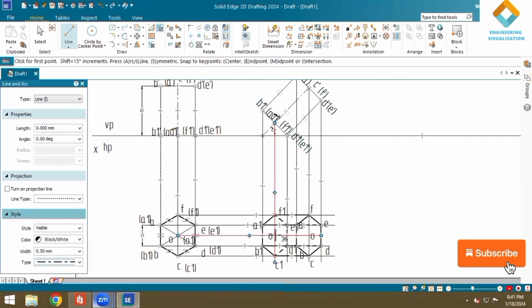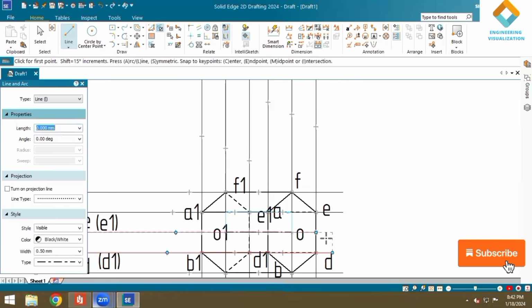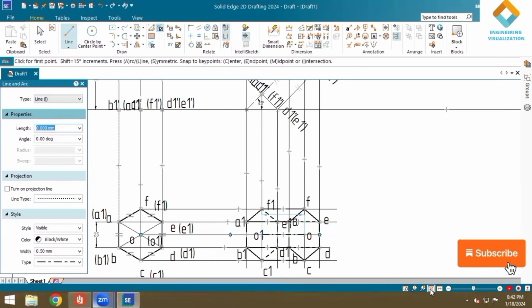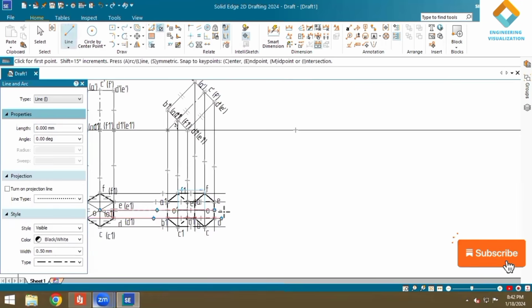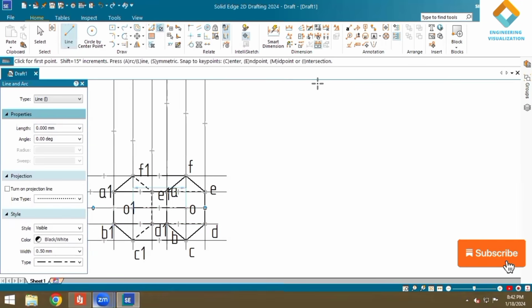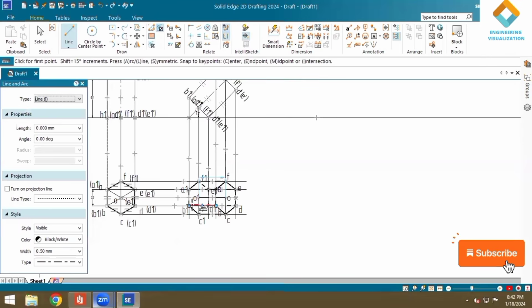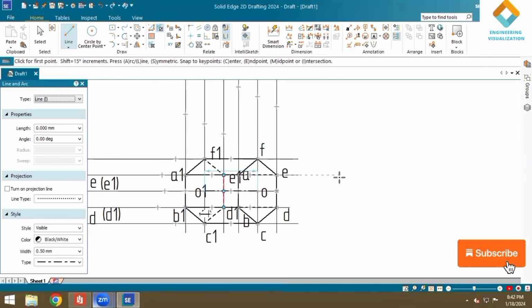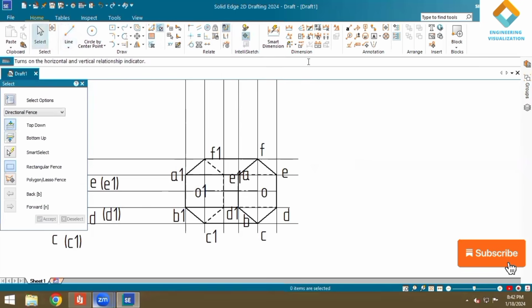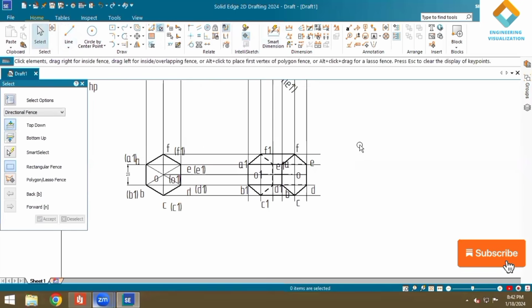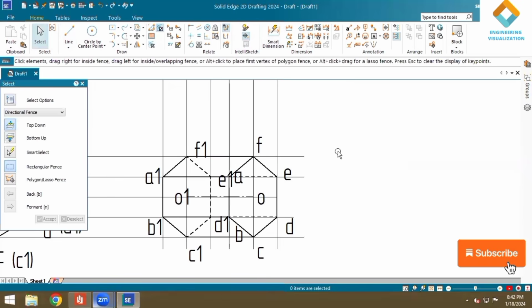Finally, there is an axis you can connect. Okay. Now in this problem, you just see they have given angle of inclination to axis for both HP and VP plane. We know the concept for beta angle. If the angle of inclination is given with respect to axis for both HP and VP, it means it is beta angle. Correct?